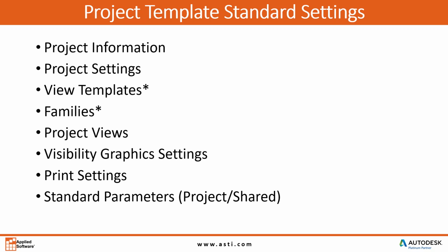If you have a custom door family, because none of the door families in Revit out of the box are sufficient for your company standard, so you customized it, and it needs to be in every template, every project from here on out. Well, those families need to be saved in a special location so that when you're upgrading your templates from Revit 2016 to 2018, those families are also being upgraded and loaded back into that template, so make sure that it works correctly. We'll talk about that again in a little bit.